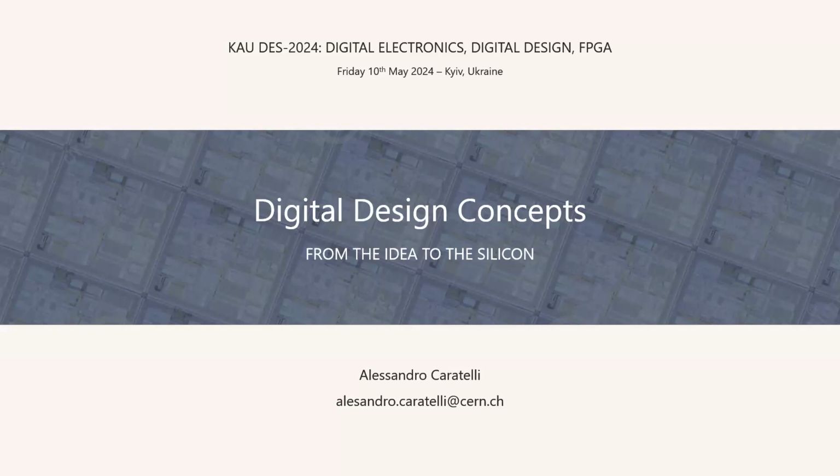With an FPGA, again, you're defining your hardware, so you can optimize. If you have something highly parallel, or want different functionality running at the same moment, an FPGA can be more efficient. A GPU allows you to parallelize, but to do the same task on a lot of things. On an FPGA, you can implement different pieces of hardware doing different functionalities, all at the same moment. So it depends a lot on the application.